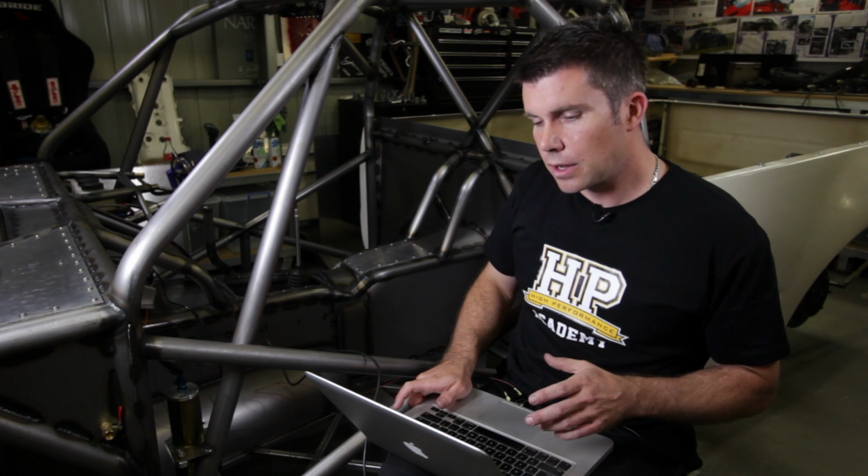It's a physical fuse, once it's blown, that's it. With the power distribution module, you can actually set it up to retry that particular circuit. So perhaps there's a really particular set of circumstances, your battery voltage is really low and that just produces enough current to trip out the fuse.